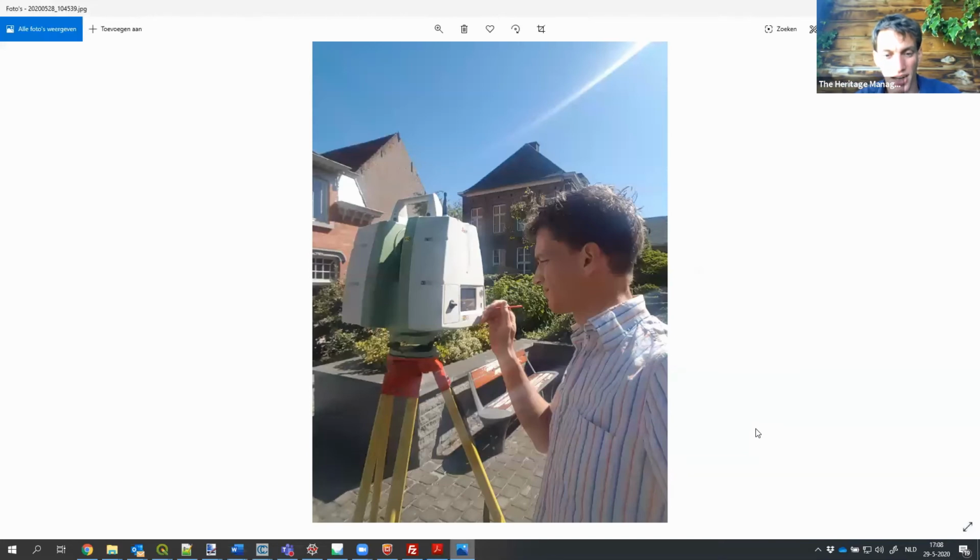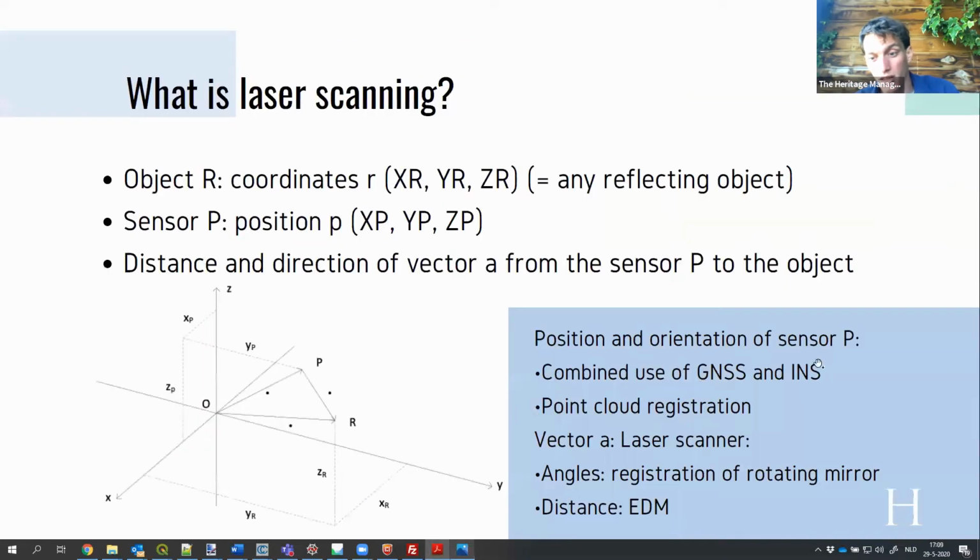For example, if I have a GPS, or GNSS to put it more generally, attached to my laser scanner, I know the absolute coordinates in WGS 84 or UTM or the Belgian national coordinate system. But in that case, I also need a system to have my orientation correct, because a GNSS only measures a point. So I need a motion sensor or a gyroscope or a compass to set my orientation straight.